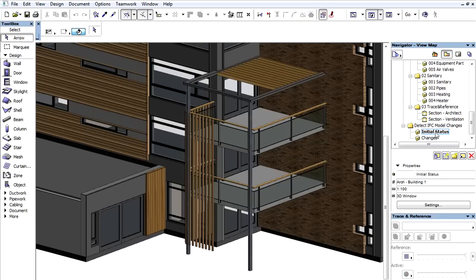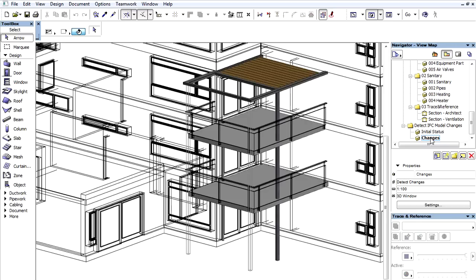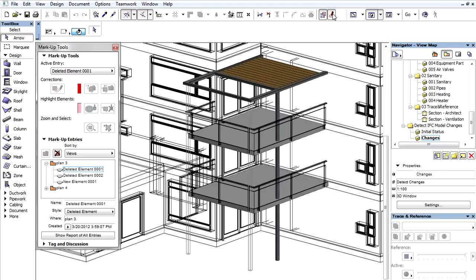A real collaboration workflow is bidirectional and dynamic, meaning there are continuous round-trip iterations. To fulfill this requirement, open collaboration requires workflow-level support for change management, where existing, new, modified, and deleted elements are handled intelligently. For example, ArchiCAD and Tekla Structures can compare two versions of a structural or architectural model. ArchiCAD merges only the changes into the project for later checking.